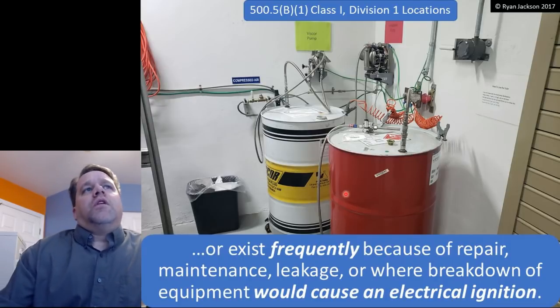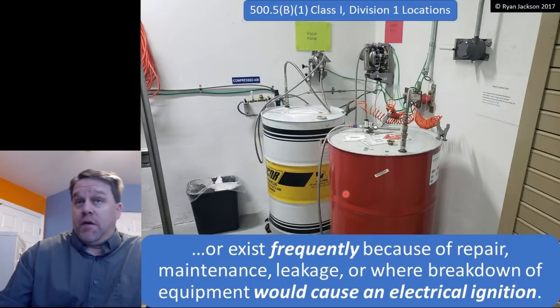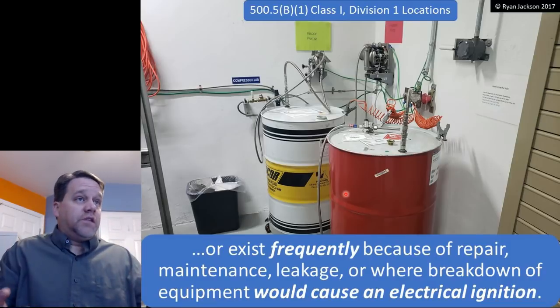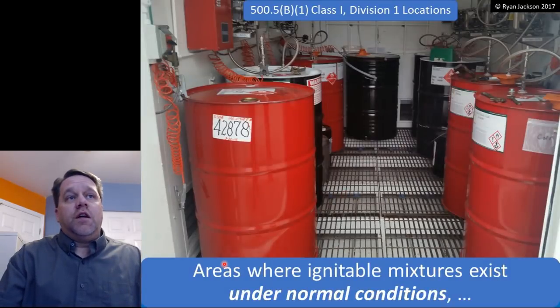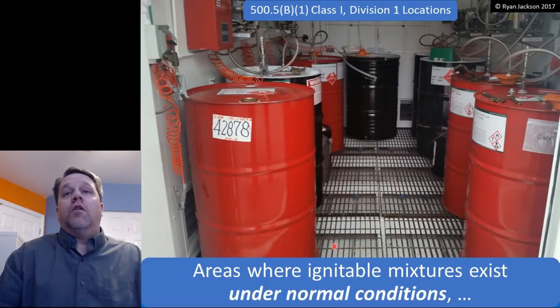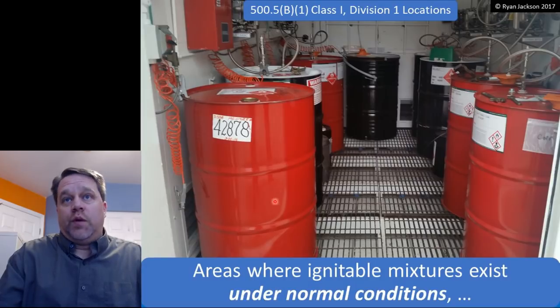So am I going to classify the entire room as Class 1 Division 1? Maybe. Maybe not. It's the area, right? It doesn't necessarily mean the entire room. It's an area where the ignitable mixture exists. Maybe from these drums down to the floor, I would classify as Class 1 Division 1. Again, I'm not telling you what to do. I'm just saying that that could be how the room is classified. Maybe from 18 inches up and then down to the floor, it's Class 1 Division 1.